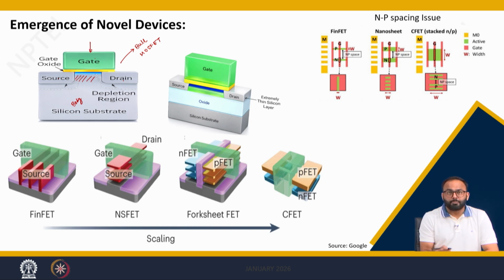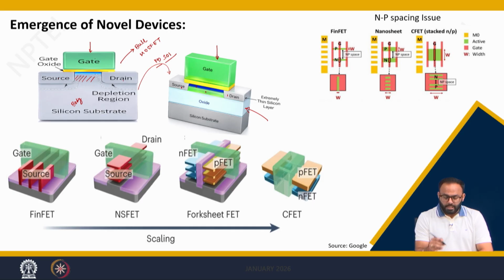and there is another problem of leakage, what we have discussed in the previous lecture. To avoid that problem, we entered into SOI structures or fully depleted silicon on insulator wafer. So, instead of having bulk, we have an oxide layer, over which an extremely thin silicon layer is grown, as this is drain, this is channel, this is source, and over this is oxide, and you mounted the gate, but still the control is from one side.